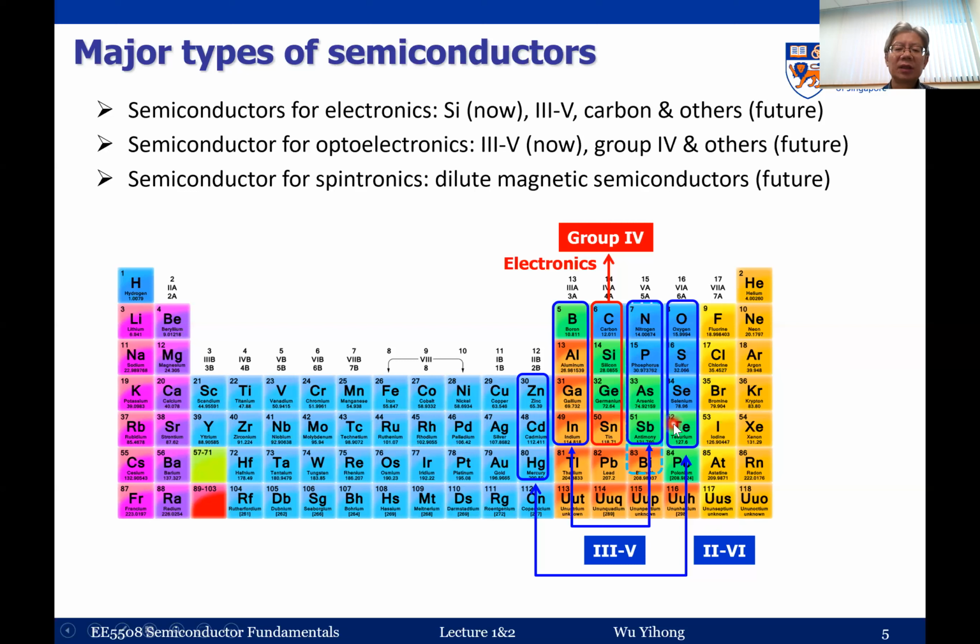In fact, at that time many large companies in Japan were working on this, from Sony to Panasonic and Sanyo or Sharp, right? And of course, in Europe you have Philips. They were all working on this kind of semiconductors. And in the US at that time we had 3M. In fact, my PhD was about this blue-green laser using II-VI compounds. At that time, we managed to demonstrate blue-green laser by optical pumping. But electron injection was very, very difficult because we couldn't obtain very good p-type semiconductors. Most of these semiconductors can be made as n-type, but p-type was very, very difficult, right?